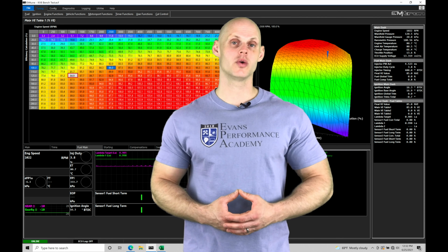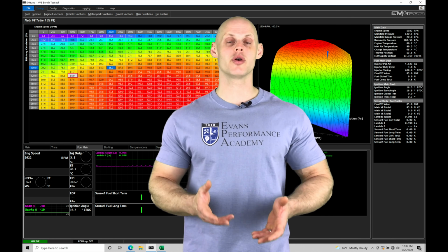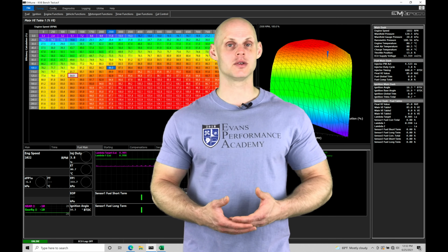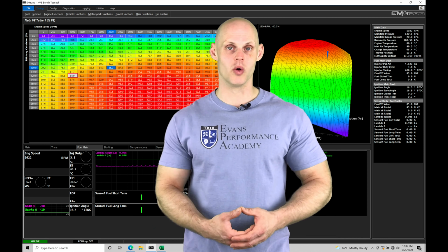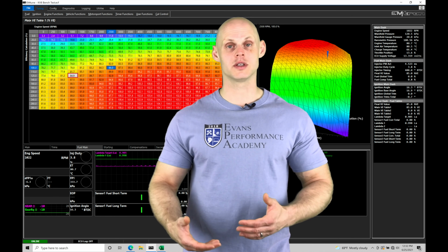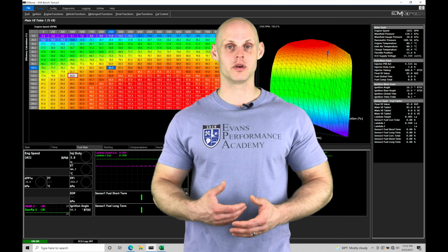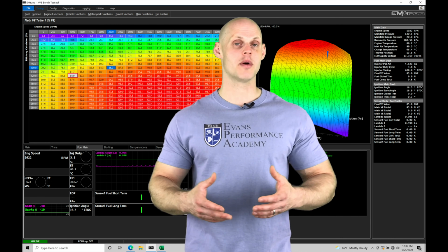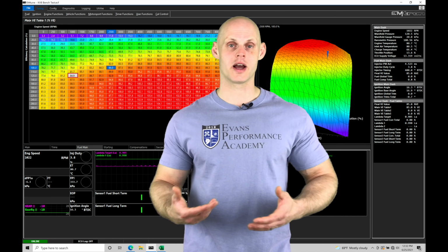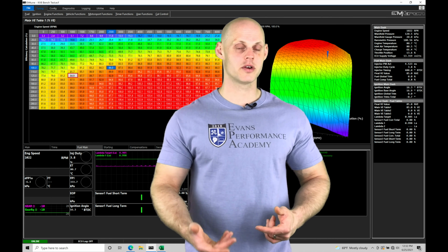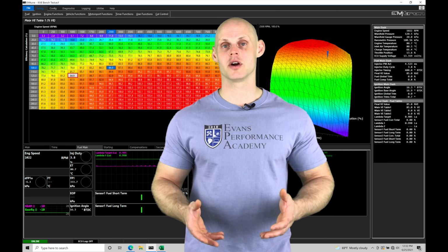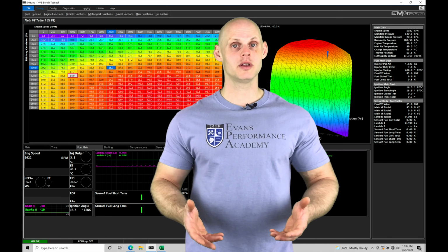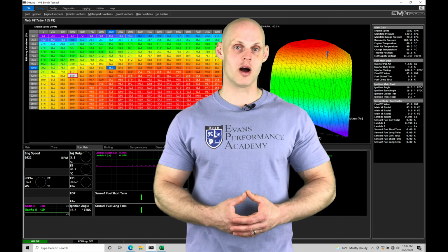In this training tutorial, we're going to be taking a look at setting up our output programming using our Emtron system. Programming outputs will vary based on what type of circuit we're trying to control. If we're dealing with a fuel pump that's low side or high side triggered, or if it's going to be a basic on-off switch or pulse width modulated, we need to talk about these basic configuration details, understanding how they work and then implementing them within our software. So we're going to go through a whole bunch of different examples here, understanding all of these core concepts and programming fundamentals. Let's jump in so we can check out working with programming our output control.